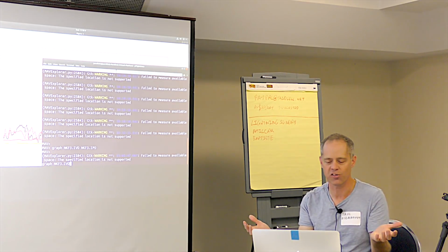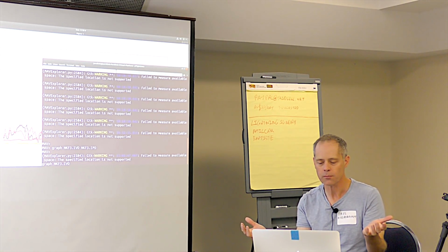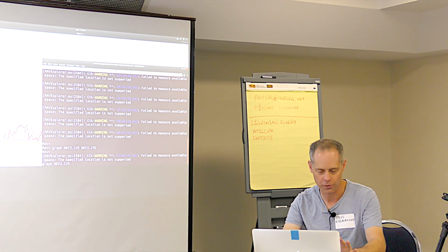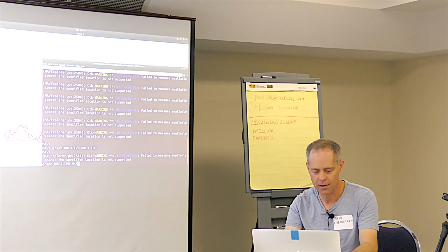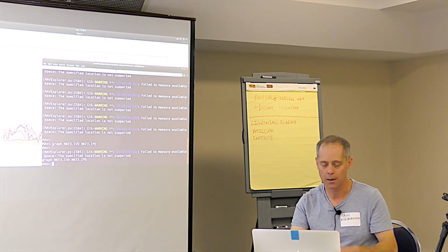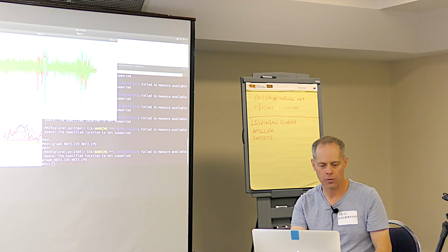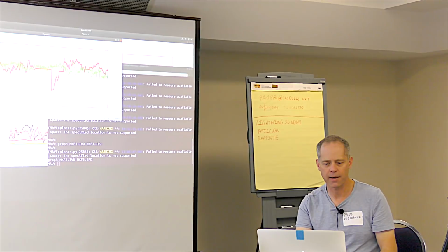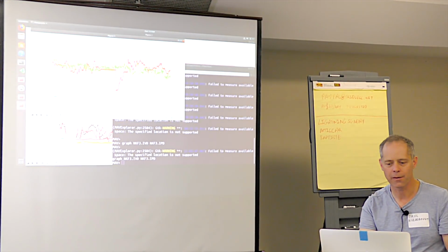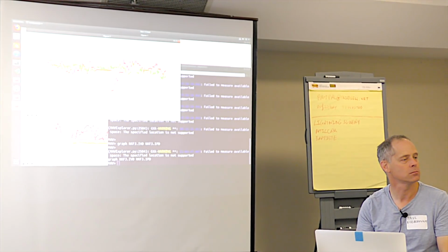I want to see, okay, what's happening to the vertical velocity innovation from the GPS? Just look at the vertical channel and EKF3.IPD, which is the innovation for the barometer. And in that instance, we can see that this was a GPS glitch.